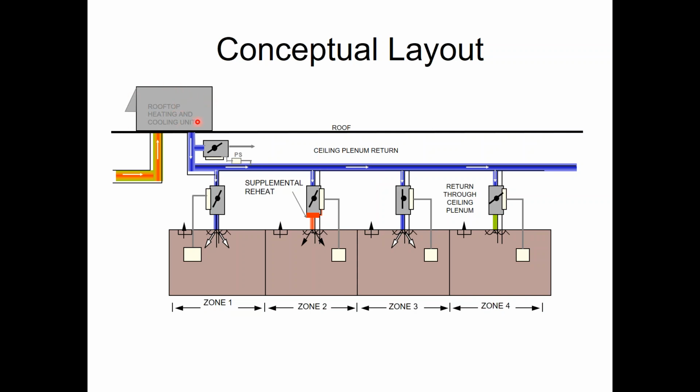The control system of the rooftop does not control the discharge air temperature. The space temperature of the zones controls how many of the 2 stages are on and whatever discharge temp you get.